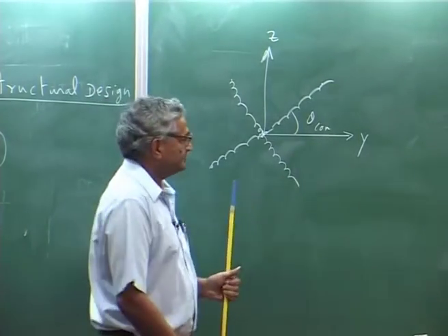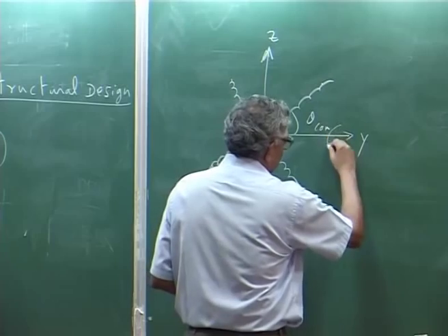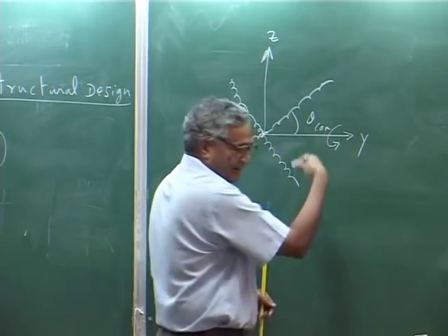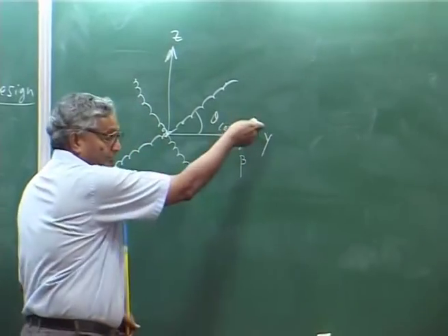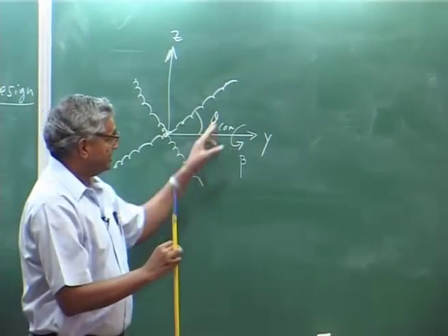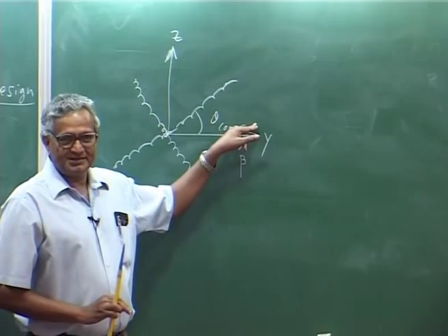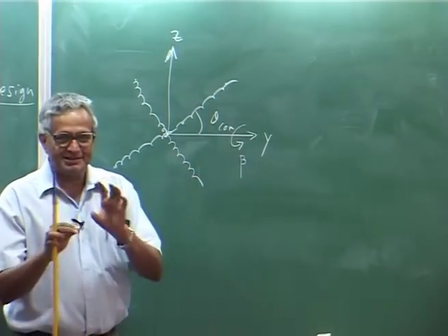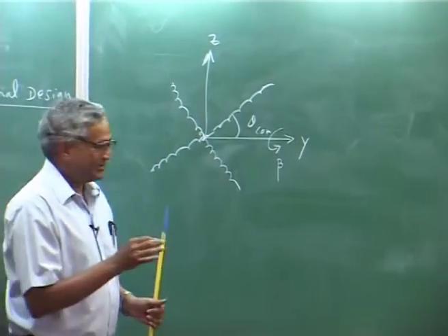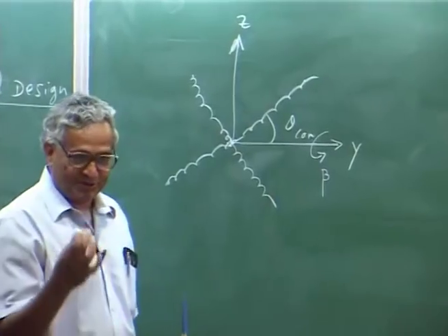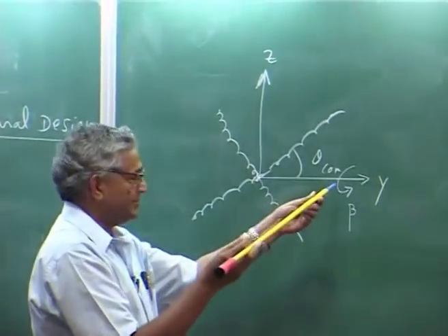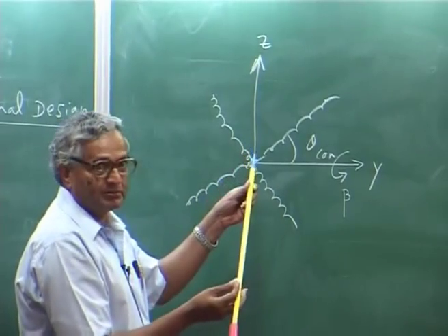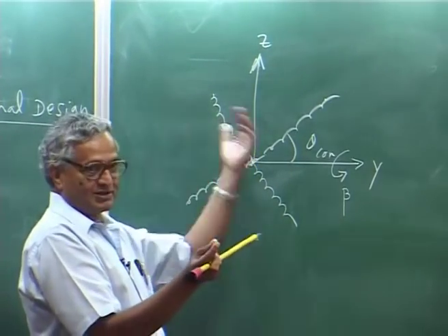If you say flap, that is flap down, I call it beta, or if I want flap up, I can put beta that side, but the sign convention will get a little goofed. In the sense, this is counterclockwise rotation, the blade is here, if I do flap this blade is coming down, even though this is the plane of rotation.